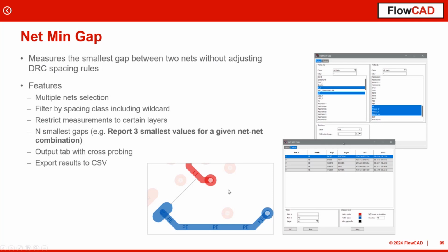They may want to measure the distances on the PCB. This sounds trivial at first glance, but we all know in PCB Editor, when you do a display measure, you can only select physical objects like a pin, a via, a trace, a shape. Yes, and of course you can measure between trace and via. You can measure between trace and shape, between shape and shape, but you cannot measure between two nets.